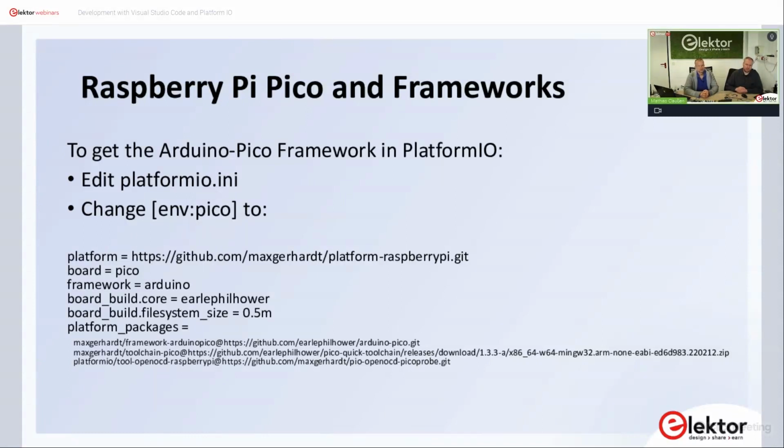That's the way to do it. It took Visual Studio Code approximately 20 minutes to process all the downloaded files and get the code in the right place and stuff like that. So be patient. But in the end, it works, and you can code your Arduino code for the RP2040 with syntax highlighting, auto completion, and also the ability to debug. Uploading is not a problem. You can have multiple configurations, so I think it's worth the trouble.